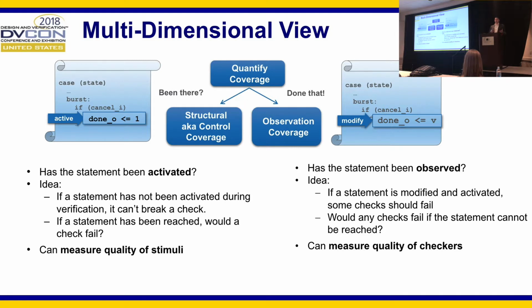So the formal engines are able to extract all possible input combinations and drive your design with those. You might be wondering why you need to worry about the quality, and it is because in formal verification, you might want to constrain out some illegal behavior, because you get 100%, and not all of the 100% is something you want to drive your design with. When you are doing constraining, it is highly possible that you will over-constrain. So you might accidentally switch off some functionality in your design, which can then mask bugs.